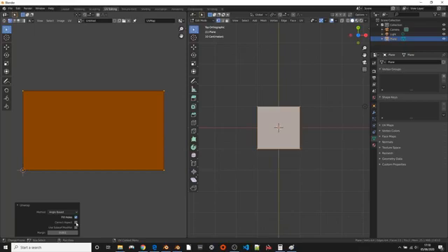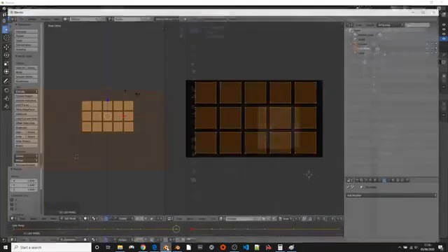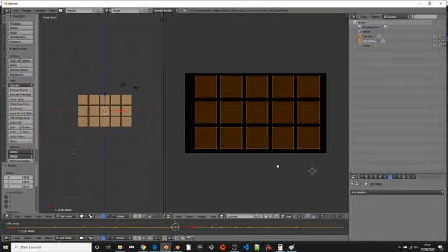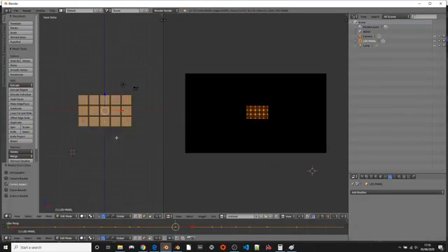This is another weird thing I see, but it doesn't change it. Whereas if I go into 2.79 and we do U project from view correct aspect, you can see here that in 2.79 that function works. So when it's ticked, the aspect is correct in relation to the object, but when it's unticked, it is not.